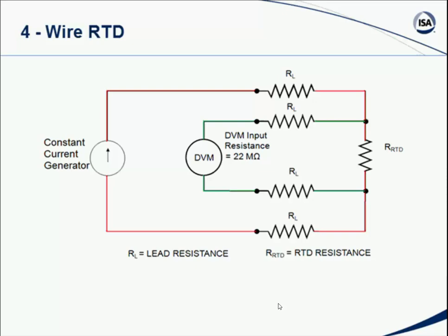One very important thing, though, is you need to understand your measurement instruments. If you buy a device, whether it's an RTD card for a programmable logic controller, or you get an RTD input board on a DCS system, it's important to know whether that is designed to take a 2-wire, 3-wire, or 4-wire device. If you try to wire a 3-wire device into a 4-wire instrument, it will not work. If you try to wire a 4-wire into a 3-wire instrument, well, it's kind of a waste of time. Really, you just have an extra lead that there's nothing to wire it to. So you want to make sure that whatever the instrument device is that you choose, if it's a device that wants a 3-wire, then order a 3-wire. If it wants a 4-wire, order a 4-wire.